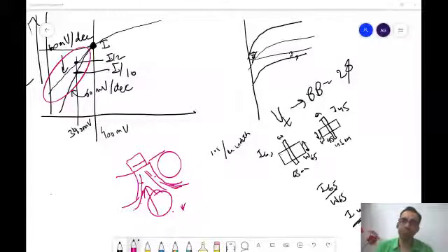Yeah, sir, one more, if you don't mind. You said that we have to apply the diode equations when we look at the subthreshold current. No, the question was that there is a depletion layer, so how is the current coming in? That was where I said it's a simple diode. A PN junction is there. You just apply the equations of reverse current in a PN junction. So the PN junction is there between the substrate and source and the substrate and drain.